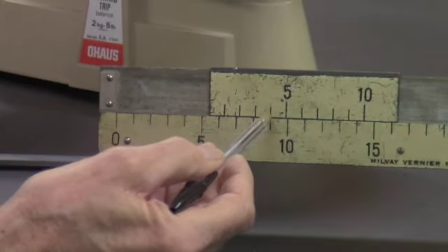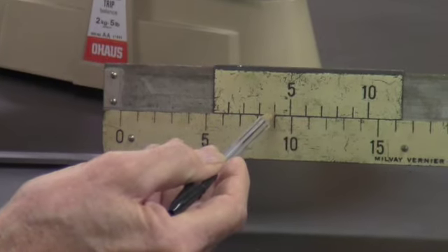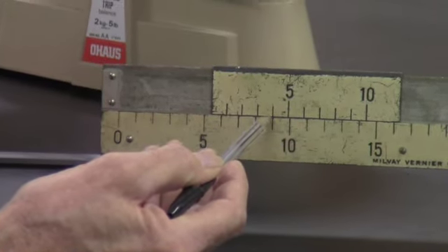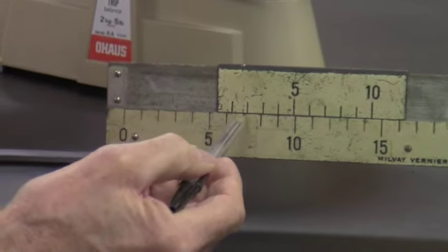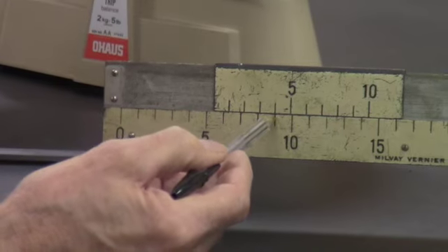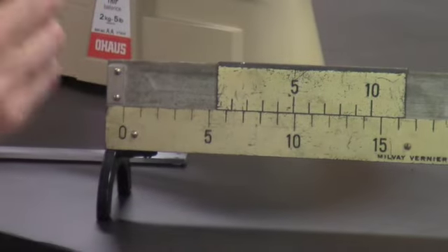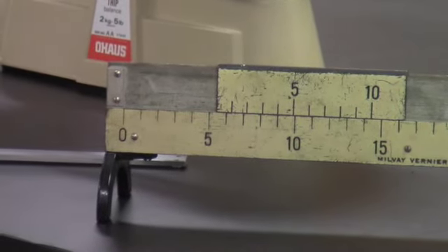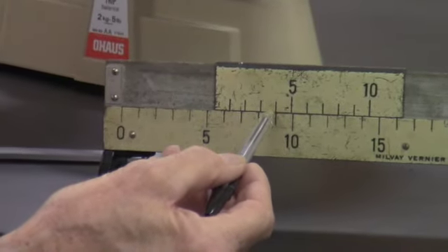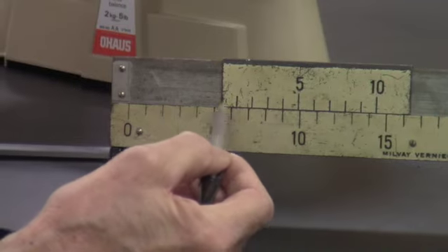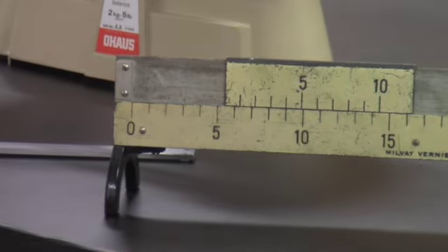And so that's because each one of these lines is closer. So the fourth line is 4/10 closer, meaning that this is 3/10 closer, this is 2/10 closer, this is 1/10 closer, and that's right on the money. So Vernier discovered you can get another honest, significant figure out of this scale using his Vernier scale. So the line that lines up best is the fourth line. So this reading is, you don't have to guess, it's 5.4.